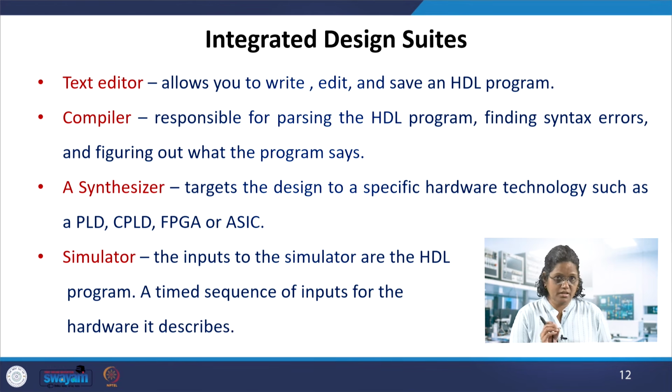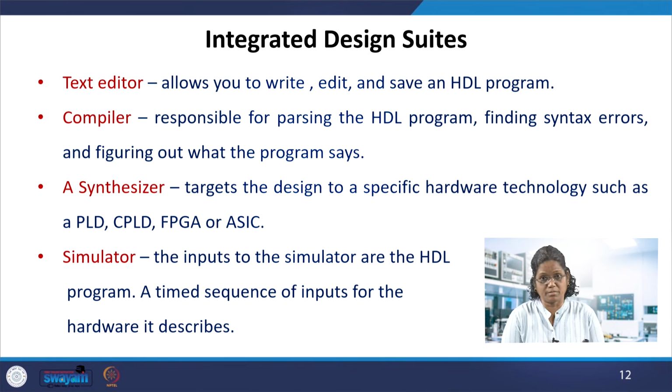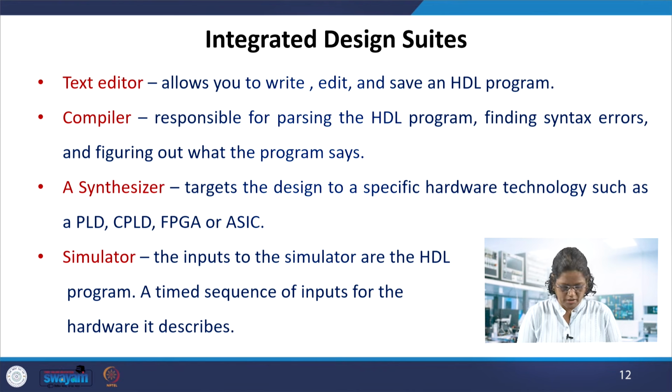And then there is a simulator in the integrated design suites that takes the input from the HDL program, that is a Verilog program. It takes what the input for my design is. Suppose I just design an AND gate and the inputs are A and B and the output is C, with 1-bit inputs and a 1-bit output. These inputs are to be specified in another Verilog program called the test bench. The inputs are taken to the simulator as time sequence inputs, and the output is decided by the simulator, depending on the functionality it has.